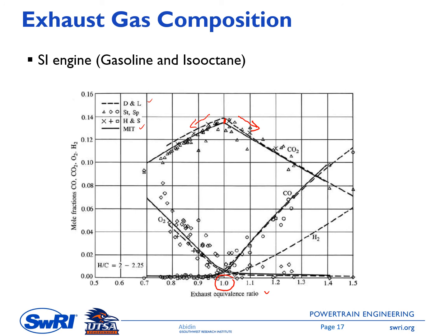If we have lean mixture combustion, it means we have more air, so the oxygen content is high. This makes sense, right? And then if we add more fuel while keeping the airflow the same, we have less oxygen in the exhaust gas. This is where we have stoichiometric, and then oxygen decreases here, although it's slow.